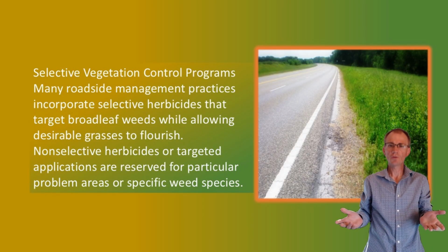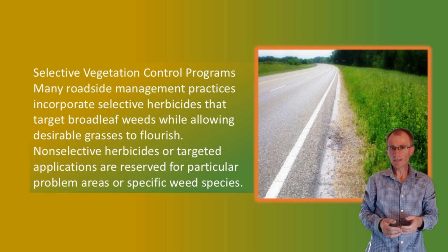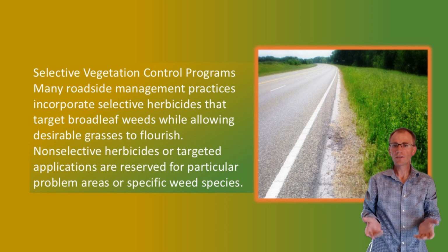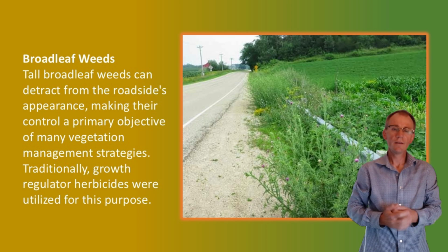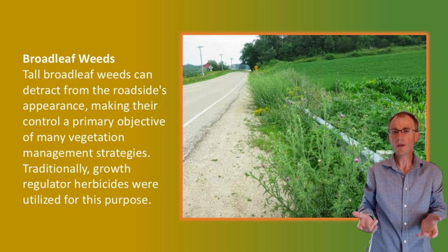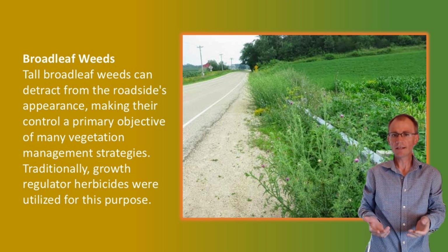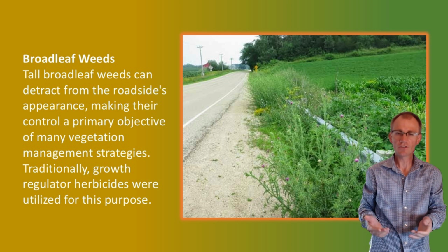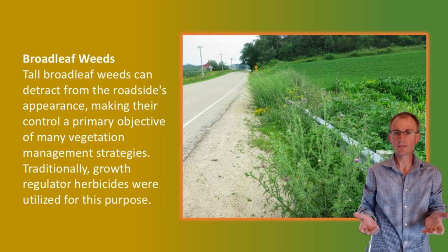Selective vegetation control programs. Many roadside management practices incorporate selective herbicides that target broadleaf weeds while allowing desirable grasses to flourish. Non-selective herbicides or targeted applications are reserved for particular problem areas or specific weed species. Broadleaf weeds. Tall broadleaf weeds can detract from the roadside's appearance, making their control a primary objective of many vegetation management strategies. Traditionally, growth regulator herbicides were utilized for this purpose.